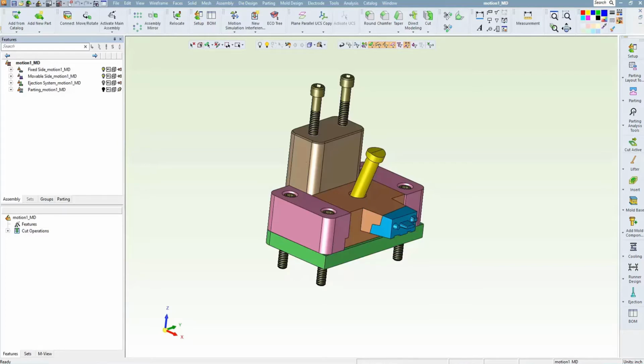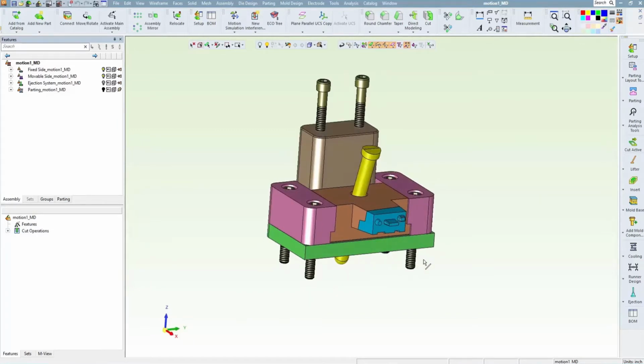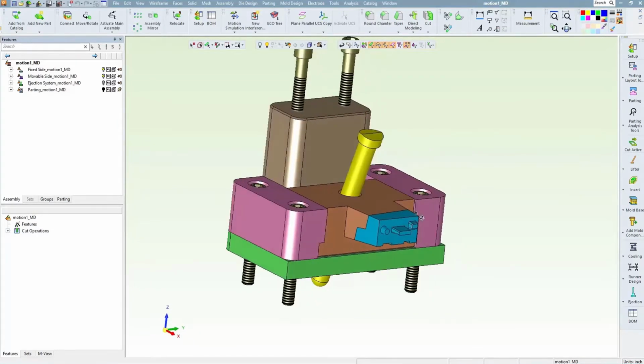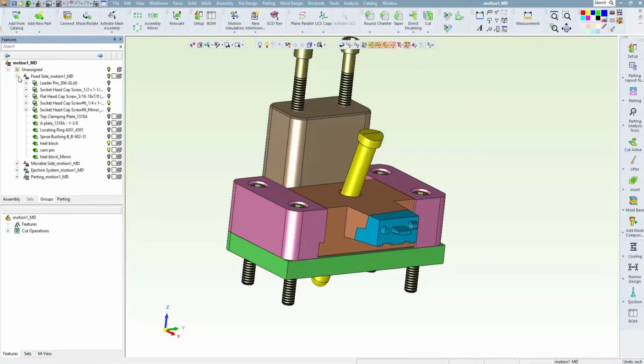The first rule on the checklist was about defining groups. But what is a group? Groups are something that can be made anytime from the dedicated Group tab on the tree. Under the heading of unassigned parts, you'll find the entire assembly tree repeated. But groups are entirely independent of the assembly tree. Any parts from any subassembly can be grouped together.